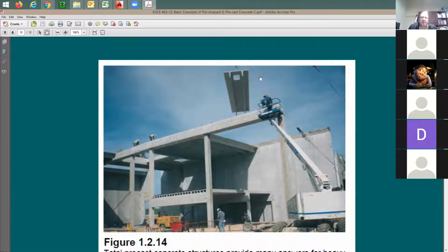What is the maximum span, or the optimum span? You say maybe about 50 feet. So this can span about 50 feet, no supports, just one piece. And this width can be maybe 8 feet to 10 feet. So just imagine how fast you can cover this area after you put the beams. It goes very fast, right? Very interesting.